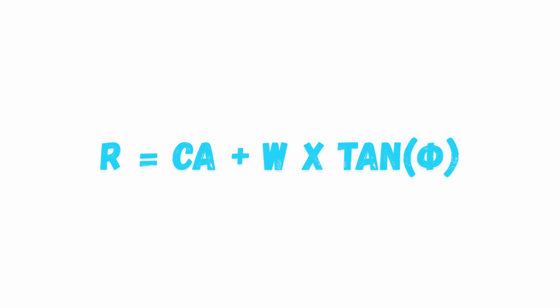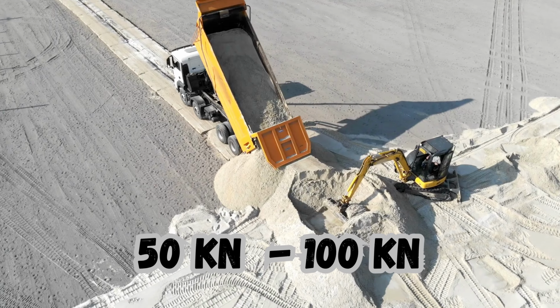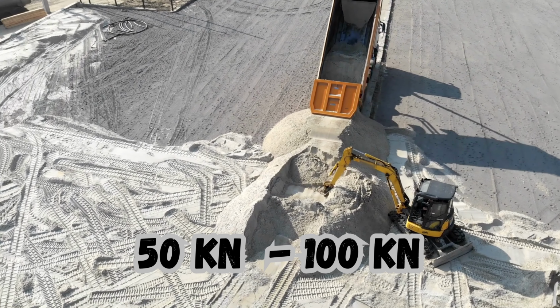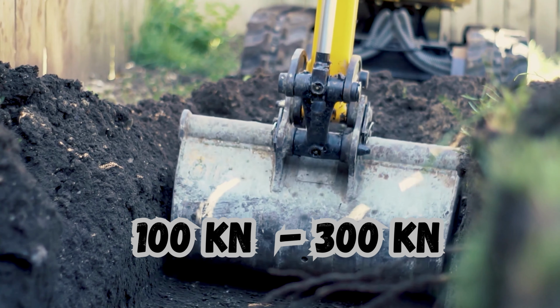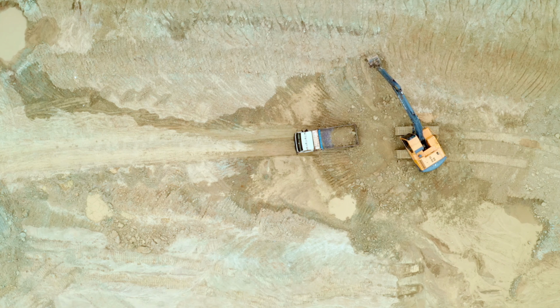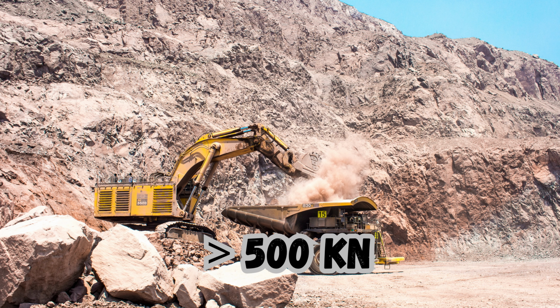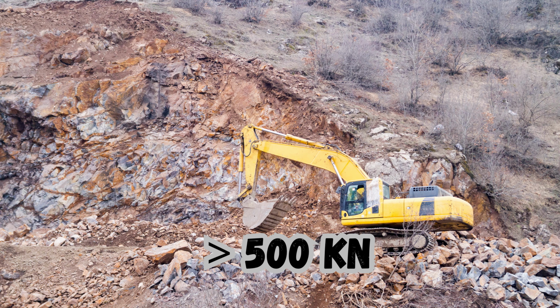The magnitude of digging resistance varies significantly depending on the soil type and its mechanical properties. For example, loose sand typically offers a resistance in the range of 50 to 100 kN, while clay soils may require 100 to 300 kN of force due to their cohesive nature. In more demanding conditions, such as hard rock or highly compacted ground, the resistance offered by the material can be extremely high. In such cases, the required digging force can exceed 500 kN.